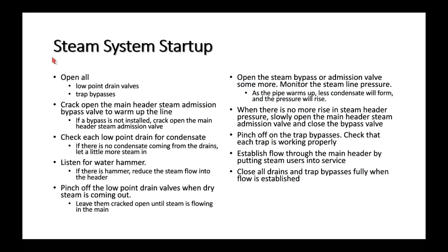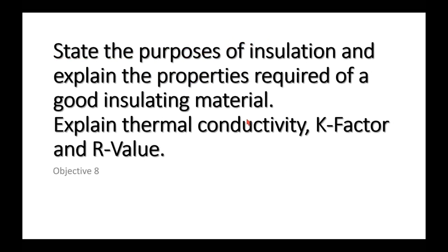So this one here is all about a steam system startup, and you have done this so many times in the Cenovus building that I'm not going to go over it. You can read on your own. It involves the rate of warm up, making sure the trap bypasses are open, and so on.